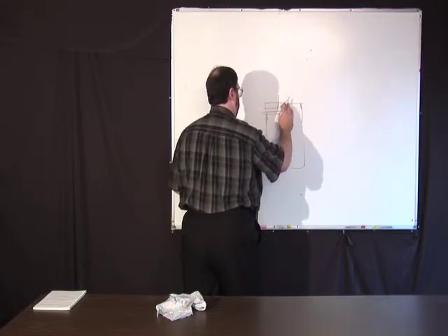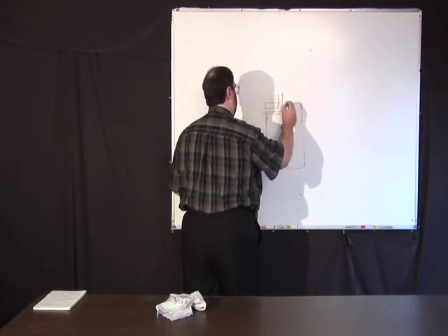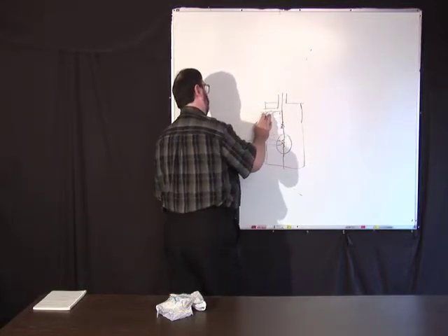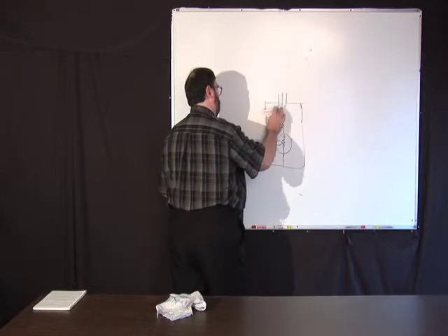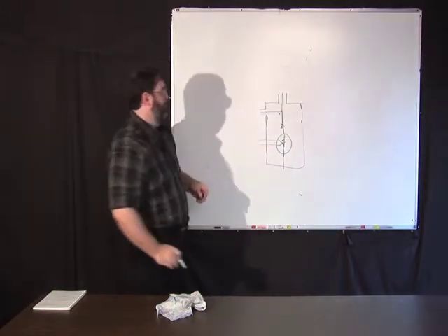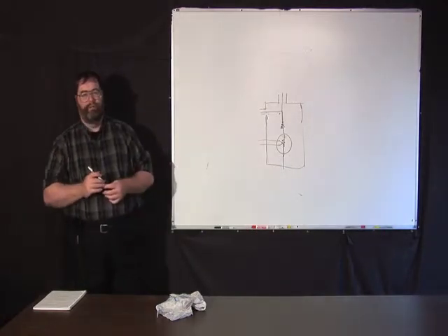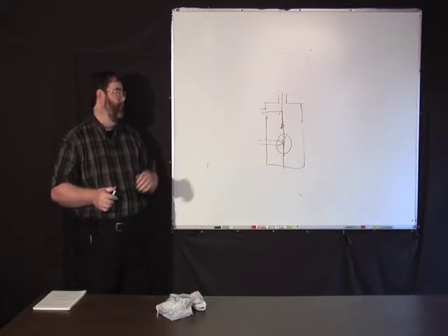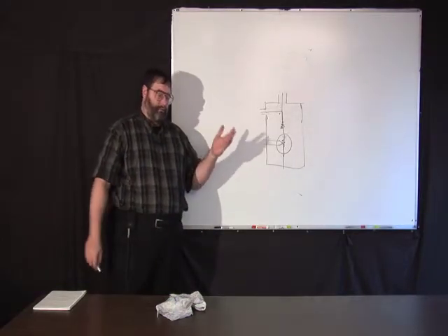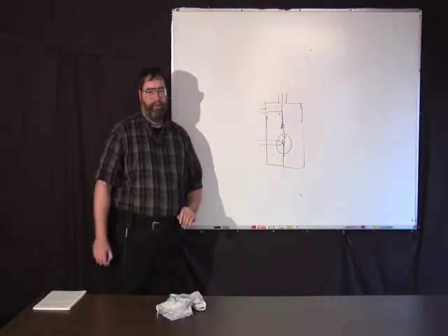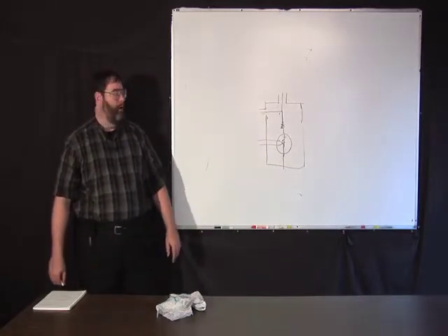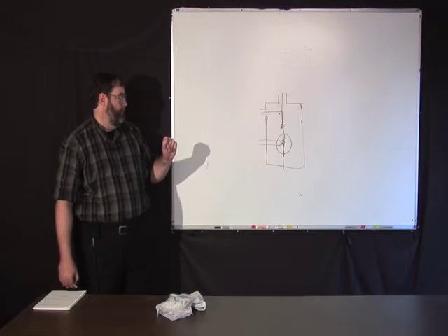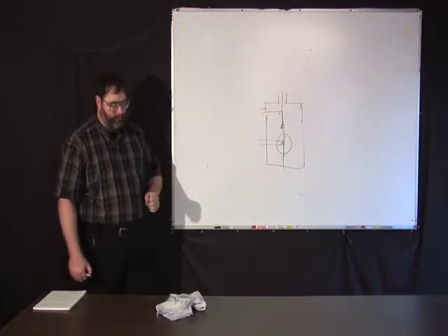Yeah, I'm not the best artist in the world. So there's usually a built-in T, because you also have to worry about transmission line effects. So you want the geometry held, because you're talking about a device that's large compared with a wavelength generally. And you don't want to change the dimensions much. So most of the RF ones are built-in T's and are used as sources.